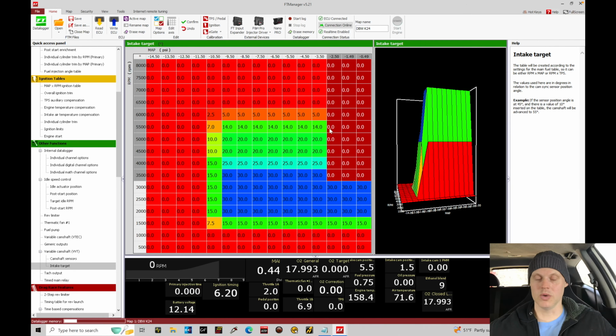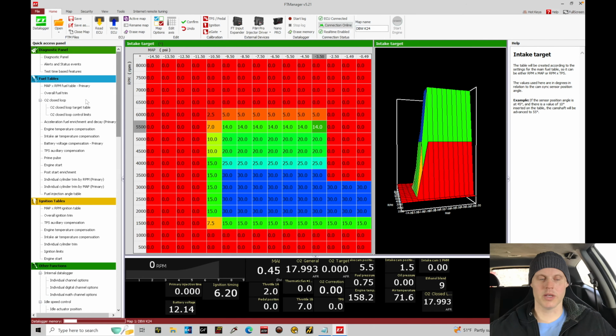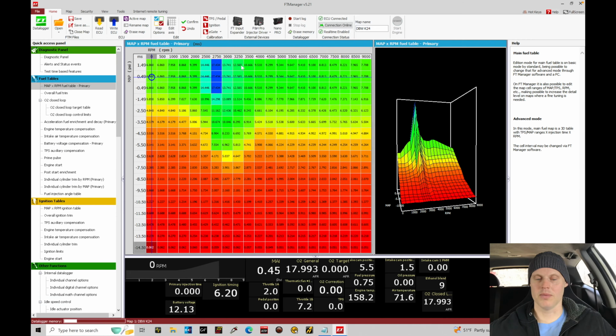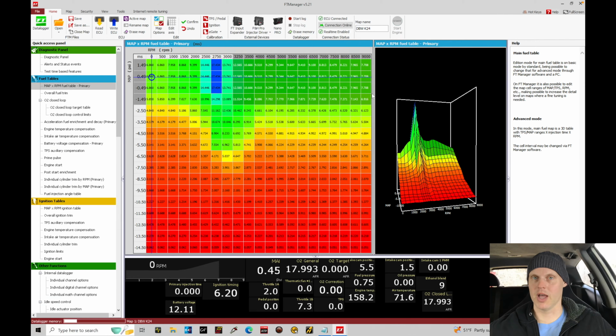Now, what we're going to be doing here is baselining at 0, going into the main fuel table, touching up our main fuel table values at 0 degrees, then walking the cam timing up, then watching the O2 correction each time we're adjusting our variable cam timing, and seeing the power differences based on what the O2 correction is showing us. We'll back up what we see in the log data by looking at the mainline with each pull and seeing if we're gaining power.